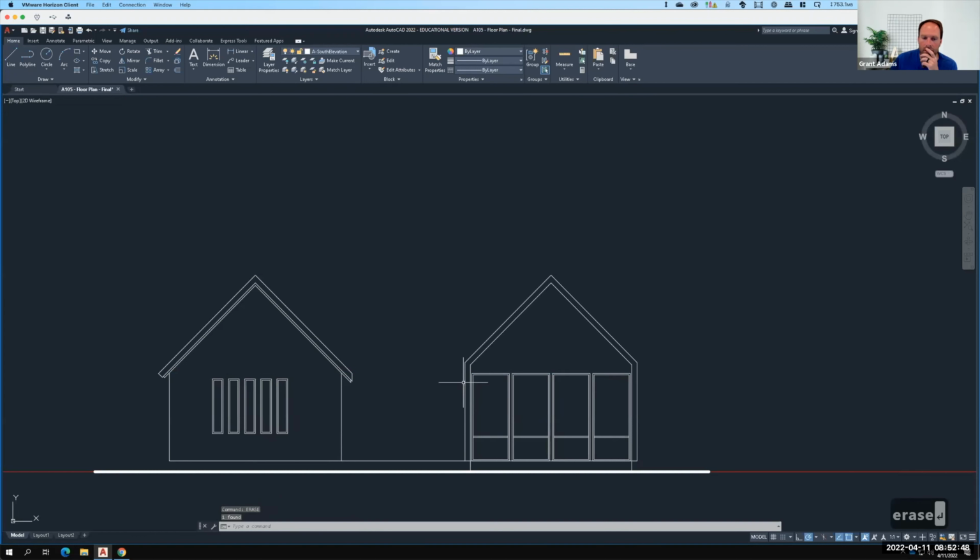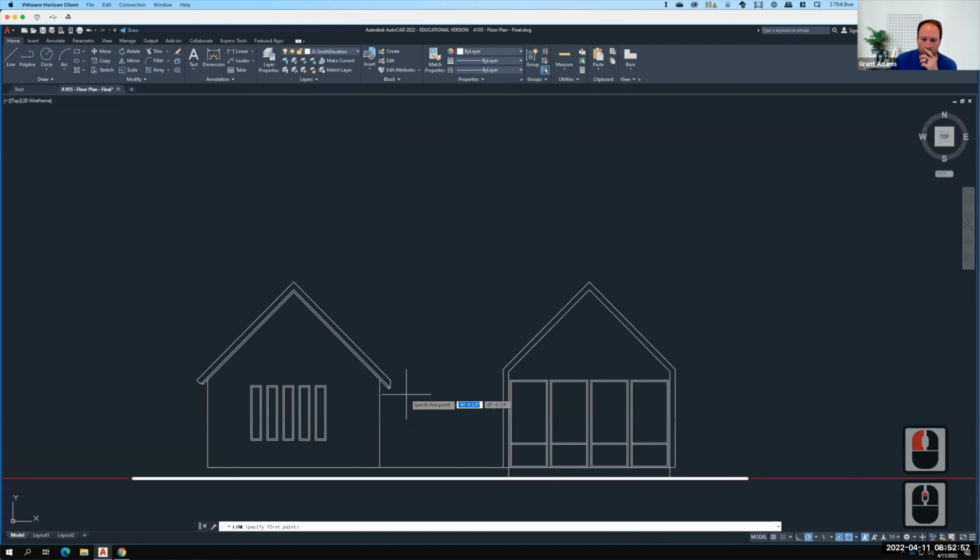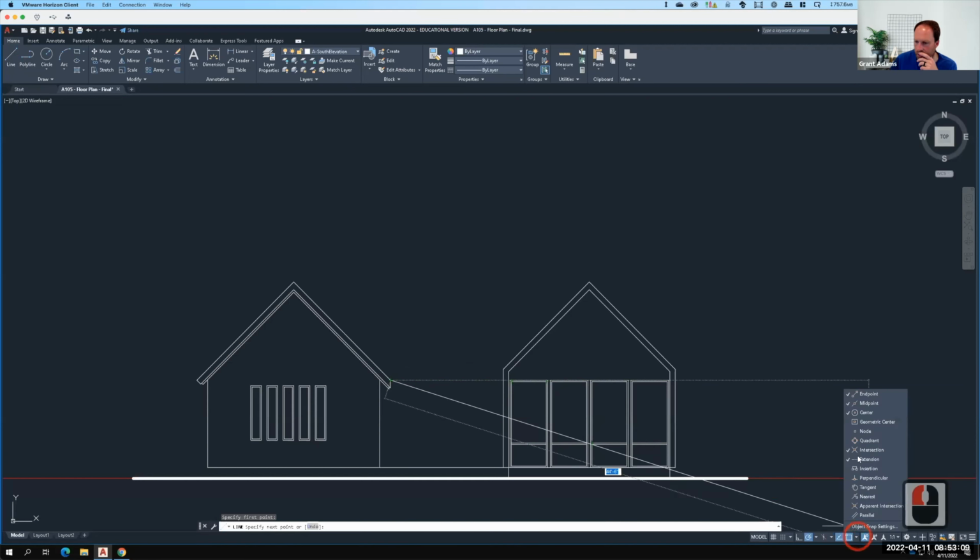There is still a bit of the building that's in the middle here. And so at some point, I'm going to need an eave that goes across or a line that goes across. It's probably going to match up right here. Oops. You know what? I don't have perpendicular snap on. I think that's part of why I'm struggling. Turn on perpendicular snap.